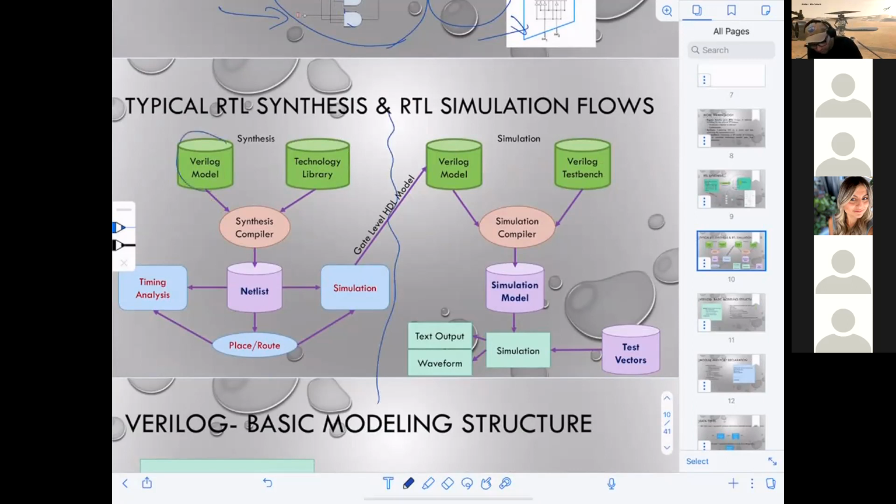I write my code. There is embedded technology inside the tool. Then I will synthesize. Then I will build a netlist, which is a bunch of lookup tables and flip-flops, and I will associate it with timing based on the critical paths that I was describing to you in the full adder and half adder example.